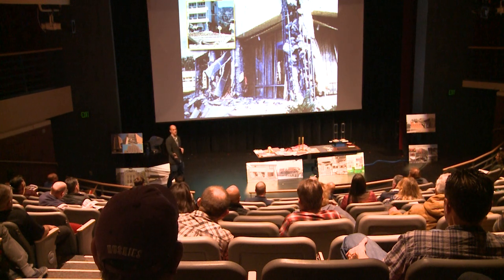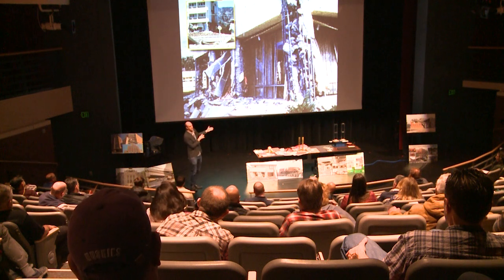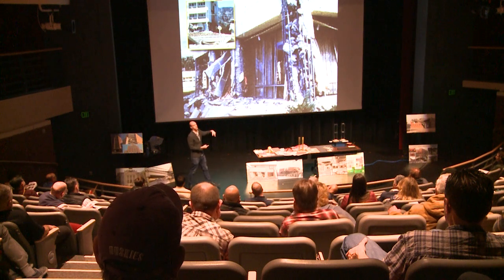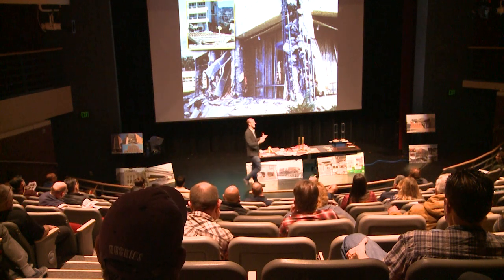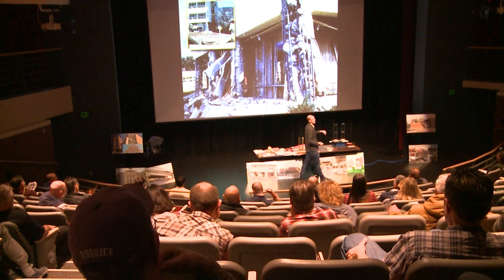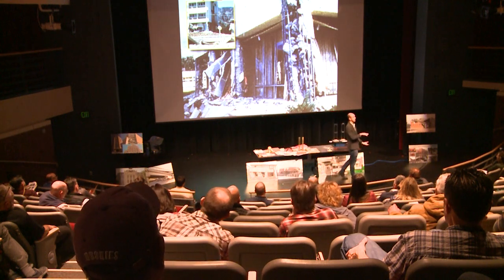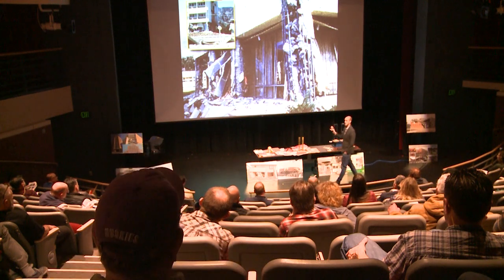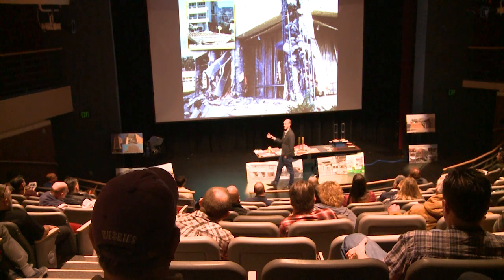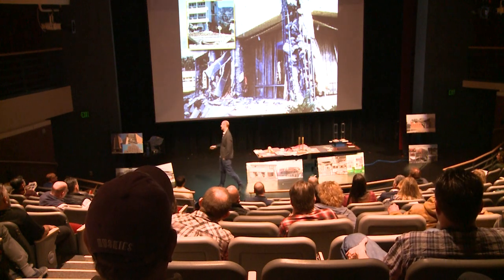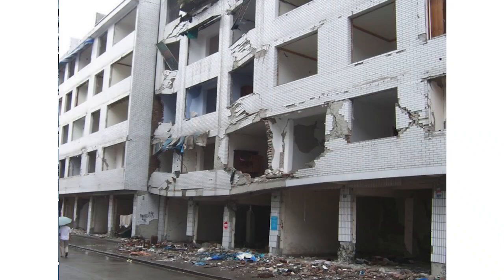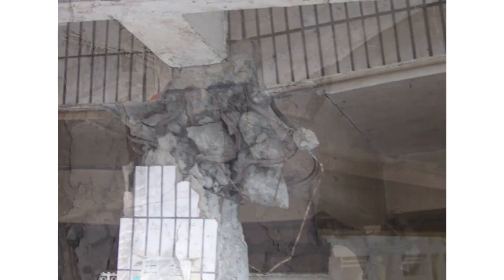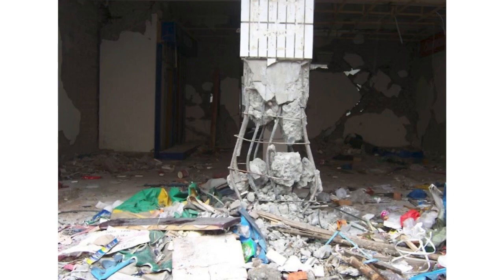Interior. The interior, because the corner one is taking half of that bay times half of that bay. The exterior one is taking double that, and the interior one is taking 4 times that. So all things being equal, the interior column that you can't see is taking 4 times more gravity load based on tributary area than the corner one. All that to say, if you see the corner one, it looks bad, probably just don't go inside the building because the interior ones are probably that much more precarious just based on the additional gravity load that they're taking. Some more non-ductile reinforced concrete damage that Rami has shown earlier.